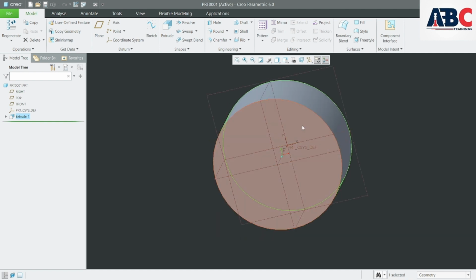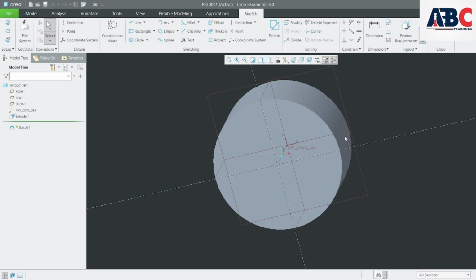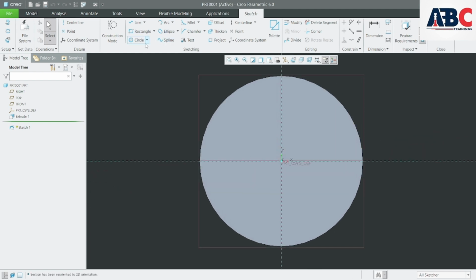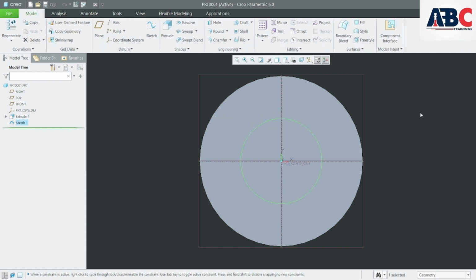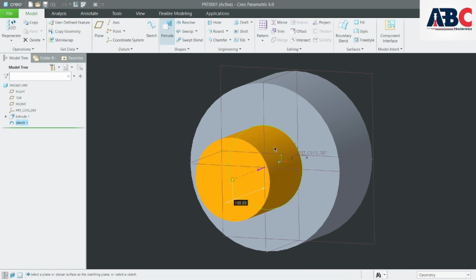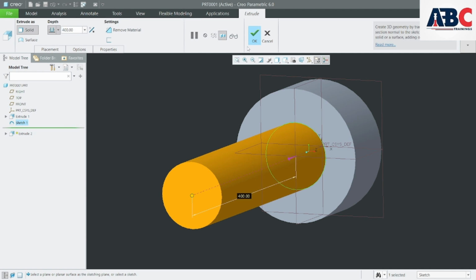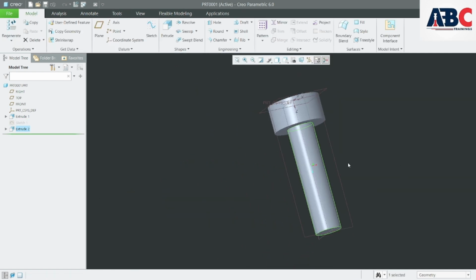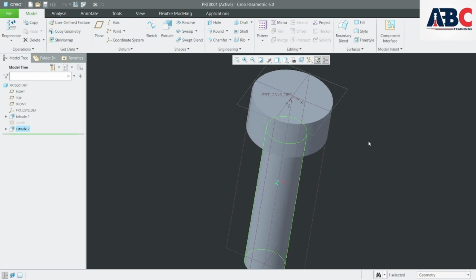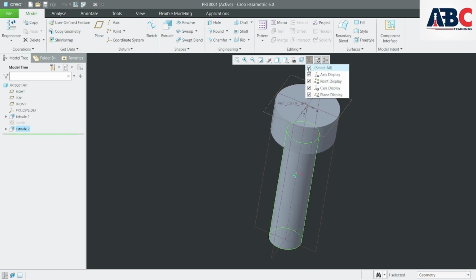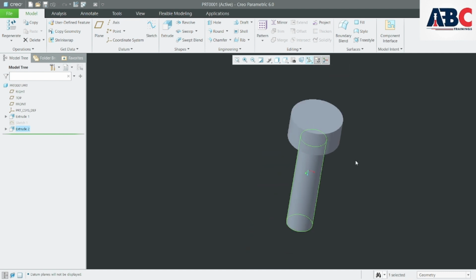Okay, now click the surface and say sketch view, then go to a circle. Let's create another circle. Yeah, this much is okay. Dimension, it's, let's say 100. Click on OK. Let's extrude the circle, make the extrusion 400. Click on OK. See, we have drawn this part. Yeah, you can see that this we have drawn.